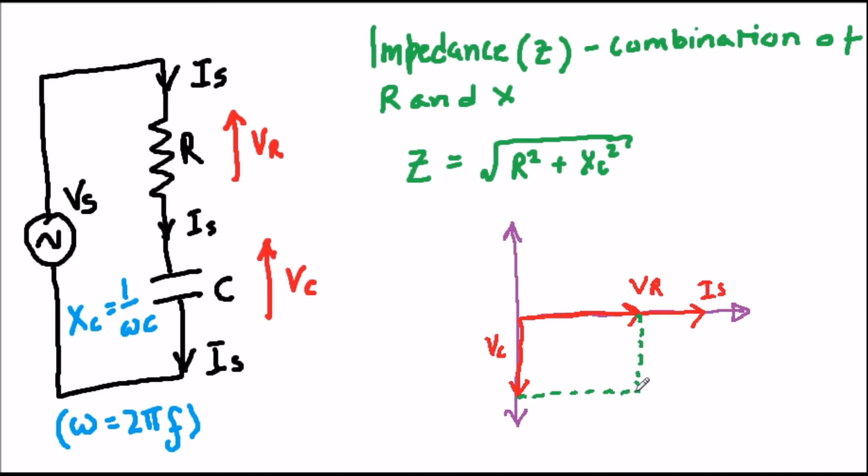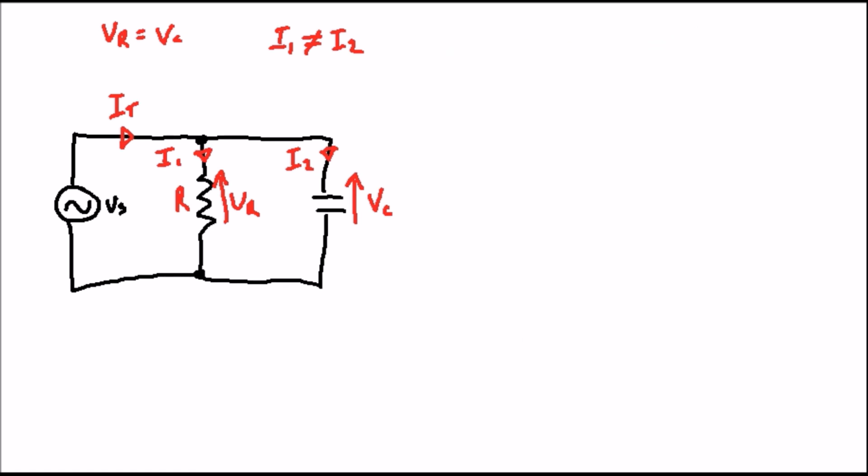And from this information, we can construct the voltage across the power source, which will be the resultant of these two voltages as shown in the diagram. From this and simple trigonometry, we can work out the angle between the current and the voltage of the supply. Let's call it theta. Incidentally, the cosine of this is sometimes called the power factor of the circuit.